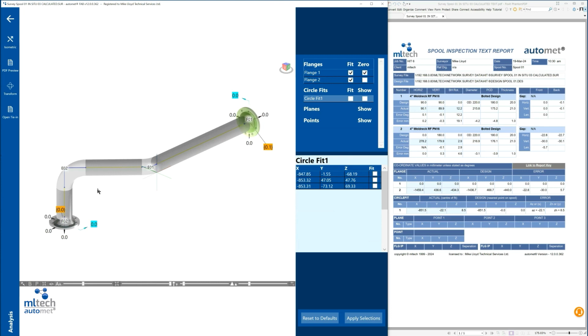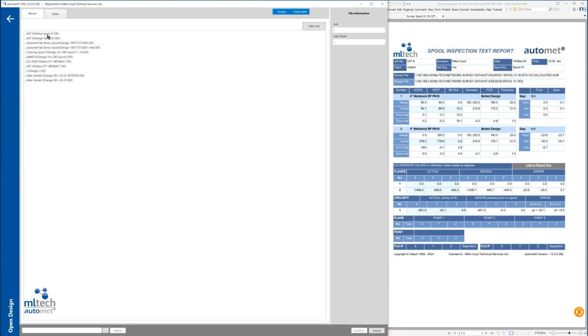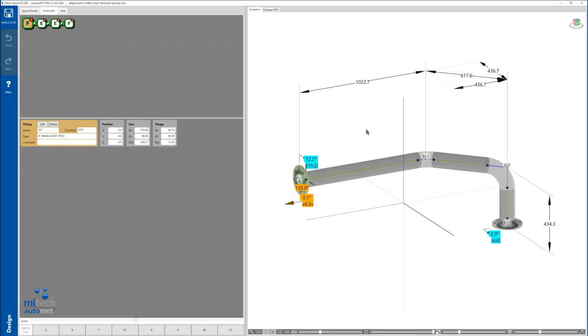If the cross-check shows errors for position alignment or orientation at the flanges, then copying the text report has not been performed correctly. Go back and redo this process again. After the cross-check, go back and clean up the deliverable drawing.